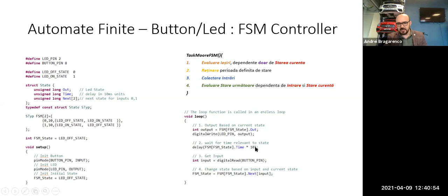10 times by 10 milliseconds. Okay, for the Arduino implementation, we can do that by the loop. But if you use a sequential or FreeRTOS system, for FreeRTOS you'll have to use the task delay function.